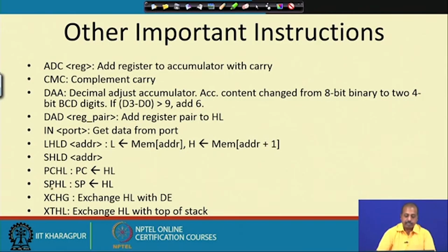Another similar instruction is SPHL. Just like the program counter can be loaded with the HL pair, we can have the stack pointer loaded with the HL pair. If different programs want to load the stack pointer differently, they can utilize the content of the HL pair to load the stack pointer.